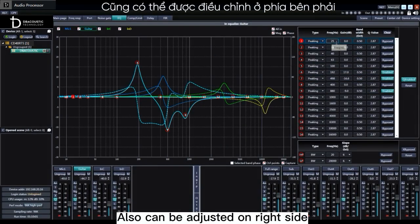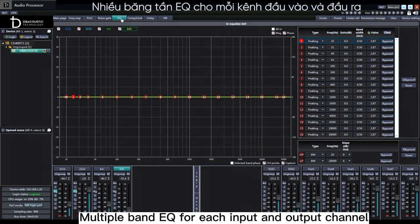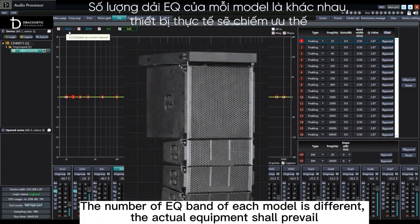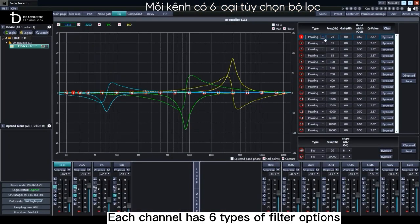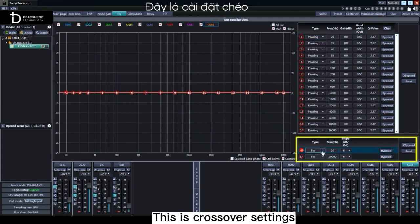Also can be adjusted on the right side. After finishing the adjustment, click to enable multiple band EQ for each input and output channel. The number of EQ bands of each model is different. The actual equipment shall prevail. Each channel has 6 types of filter options: peaking, notch, the first all pass, the second all pass, high shelf and low shelf.